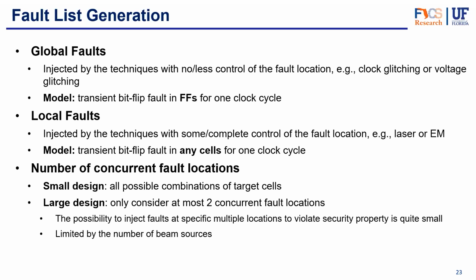All right, let's take one more question due to time limitation. Do you validate theoretical faults by implementing a real physical attack, or is everything simulated? Right now, everything is simulated, but one of my students is working on validating on FPGA, and we could actually show one of the properties right now, but we haven't tried the rest because it's ongoing. That's part of our plan, definitely, to validate all of our results using FPGAs. It's possible at ASIC right now, but FPGA is a more practical way to do it.